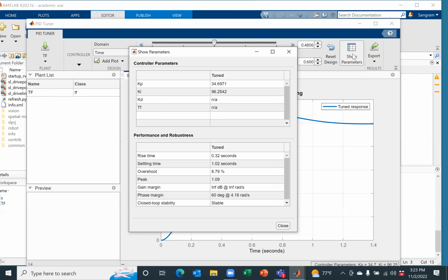And then there is a concept called successive loop closures. For an example, on the robot you will have an innermost loop that is controlling a certain part of the robot. Then you will have an outer loop, and gradually those loops keep becoming bigger and bigger, and the overall system gets controlled. But at the end, if you want to use the PID, you have a nonlinear system, you find the linearized approximation, find the transfer function, and then actually use the PID control,